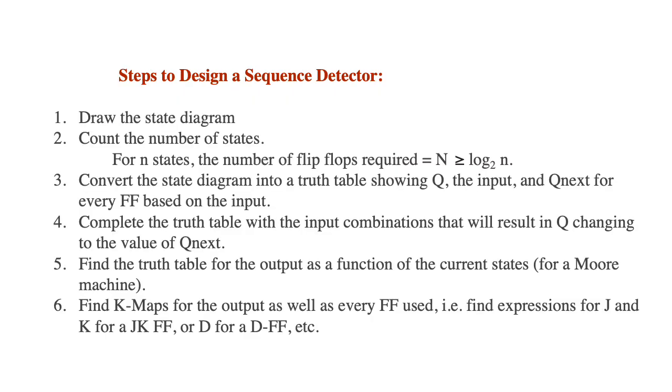Here's a list of the steps needed to design a sequence detector. Feel free to pause the video to read them on your own, but we're gonna explain them as we see an example of a sequence detector one step at a time, and then implement that step. But remember that the first and most important step is to draw the correct state diagram for the sequence detector.